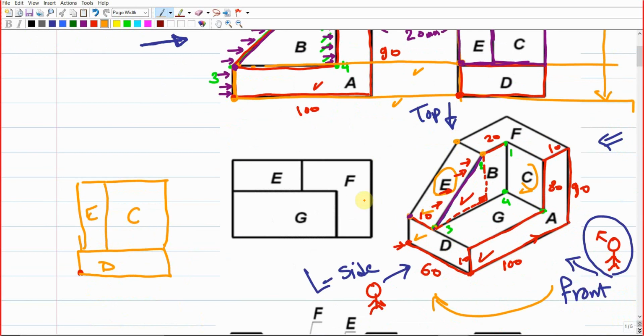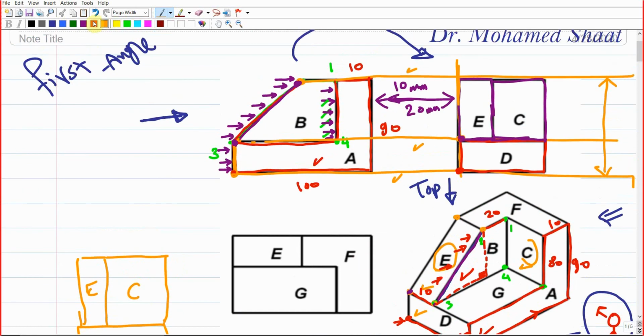view. And let us do the same for the top view. For the top view, if I ask you to look at it from the top, these are the faces that we're going to see, right? All of these will be seen, including even this inclined surface. So as you can see, if you look at the shape from the top view, you're going to see this horizontal line, this inclined line, and this horizontal line, but you aren't going to see any vertical line.